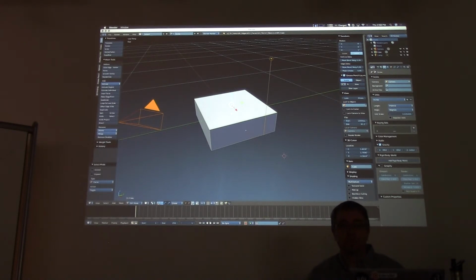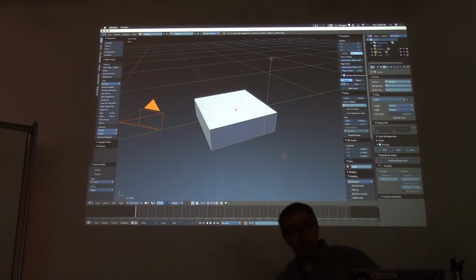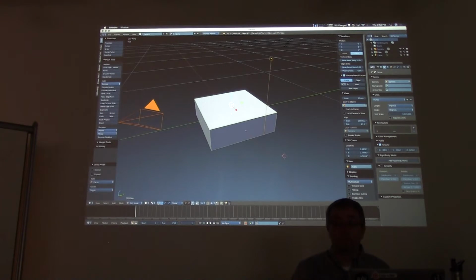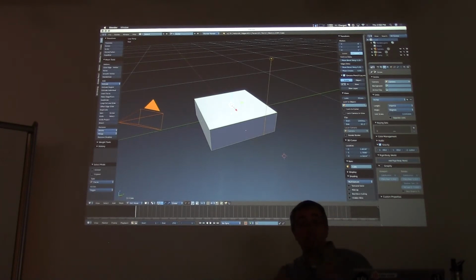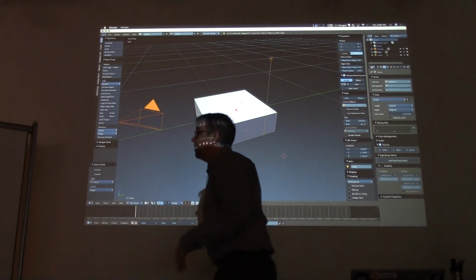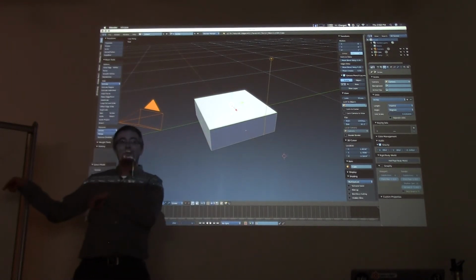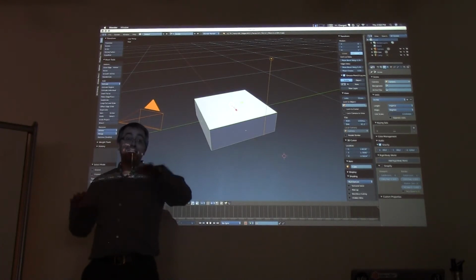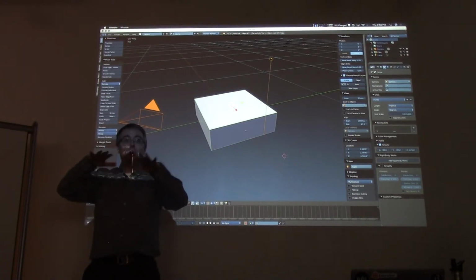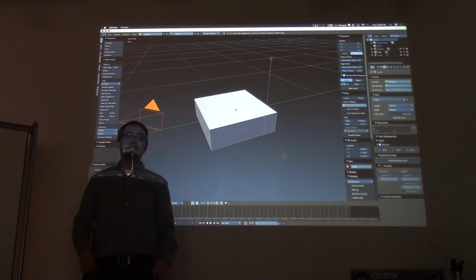Okay. All right. So I'm in edit mode, I deselected everything, I switched to face selection, and then I just grab the face I want. At this point, I want to turn that into a vertex group. One of the things you all may have noticed was that at this moment, I can grab one face, make a vertex group, and then when I cut and slide later, it keeps all of those new faces in the same vertex group, which is really handy.